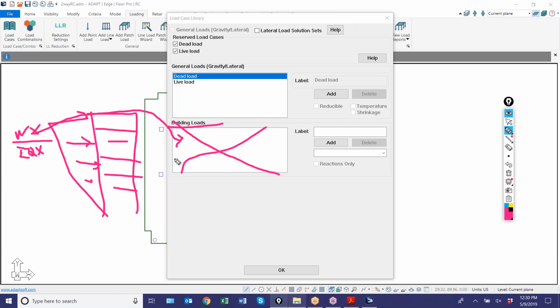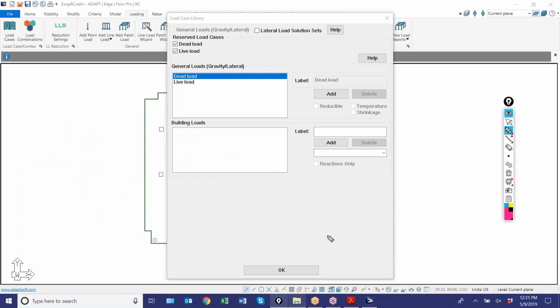model in multi-story mode. So they don't really apply to a single level structure, because when you get lateral loads on a structure, usually unless it's a construction lateral load for some special consideration, usually the building is in service and the load set would apply to the entire building, not just one independent level, in terms of that particular model. So we're going to ignore this today. We'll come back and talk about that in a different webinar as part of our series here, but we're going to mainly focus on these 2 loads for the example.